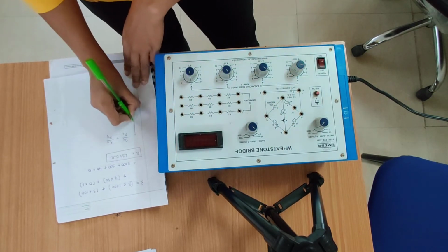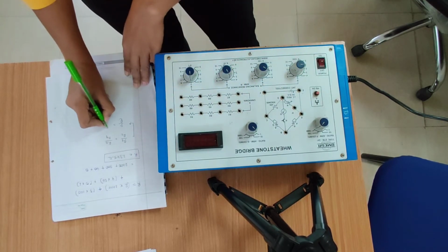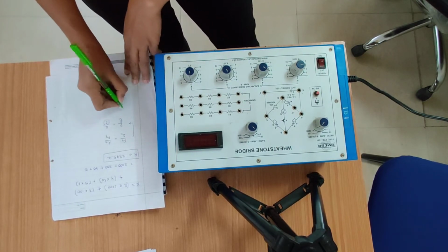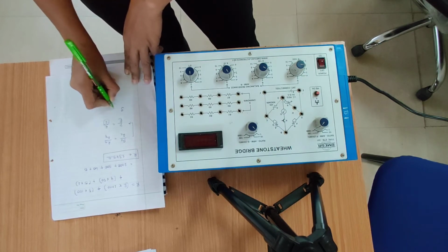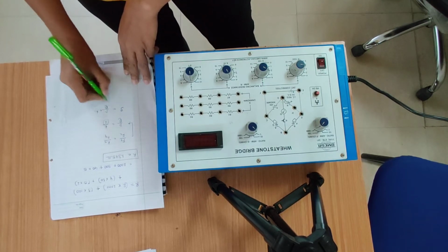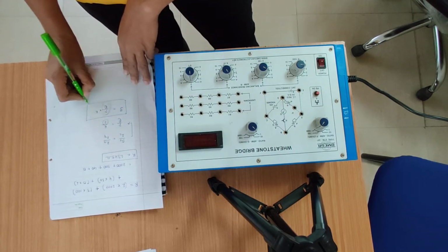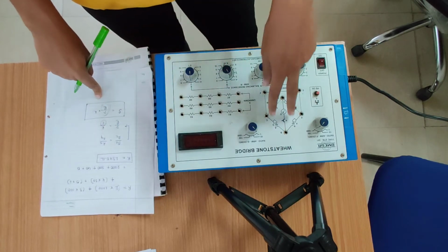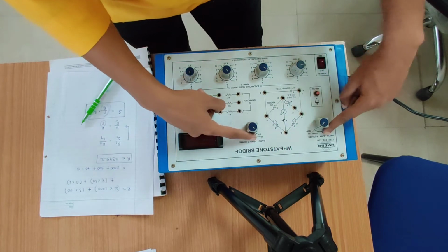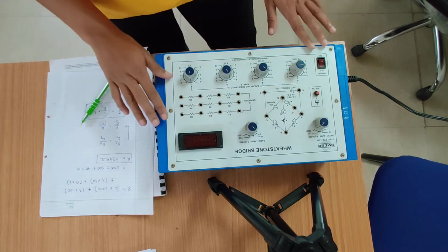So if I write this in terms of PQRS, then it would be P divided by Q equals R divided by S. As my S is the unknown parameter, if I take the value of S, then it would be P divided by Q into R. We have the ratio of P and Q in the final equation, which is the balance condition equation for the Wheatstone bridge. That's why P and Q are also known as ratio arms, as written over here, ratio arm P, ratio arm Q. Okay, I think I am clear up to this.